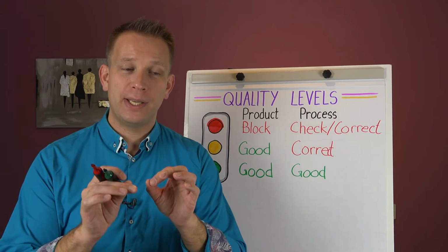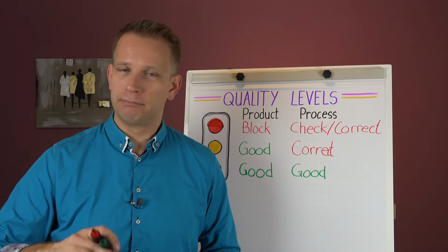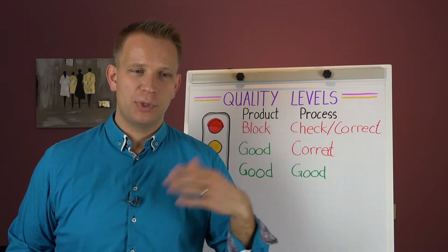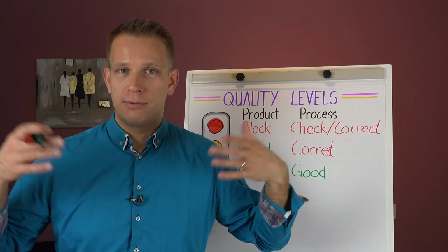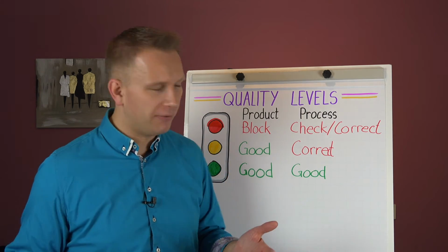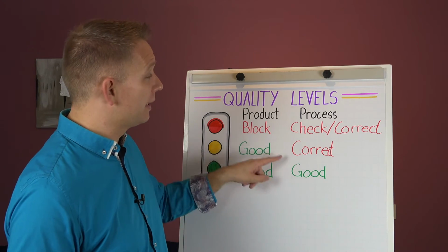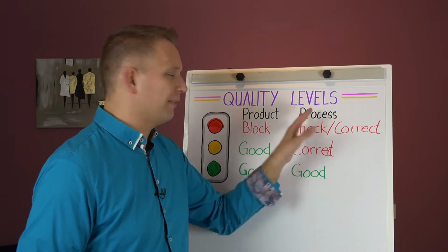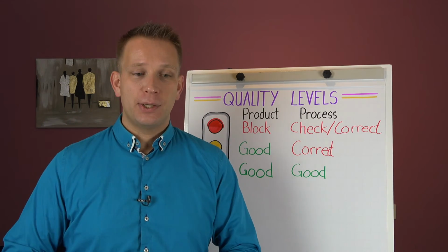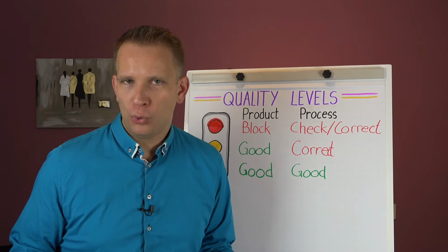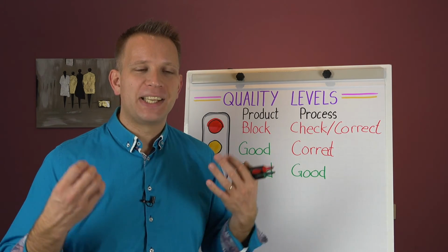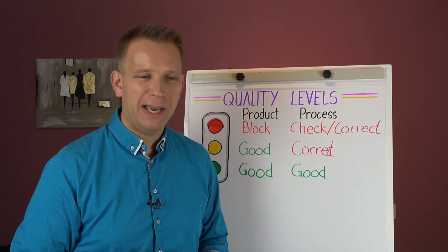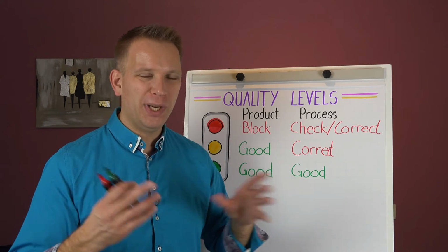So also here, again, if you are starting it up, just put the red limit pretty tight, check what you are doing, which decisions you are making, and loosen those limits based on the decisions you took every time. Document that pretty well, but you will make them into process parameters. Now, on how do you check if the process is good or not? This is where you can use this old experience and data and the things that you've learned about your process. So when the moisture level goes up to a certain amount, it's not bad for the product yet, but we know that it'll cost the company.